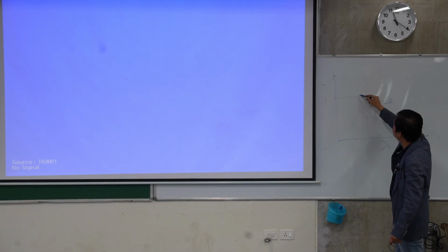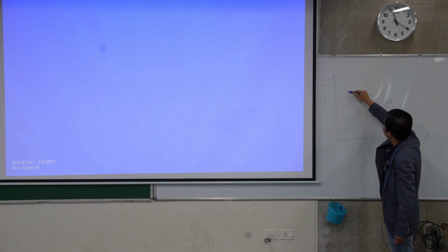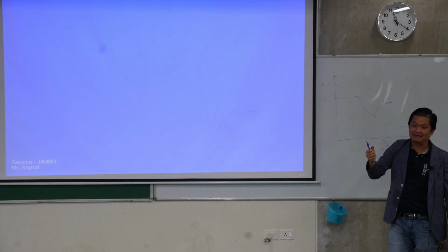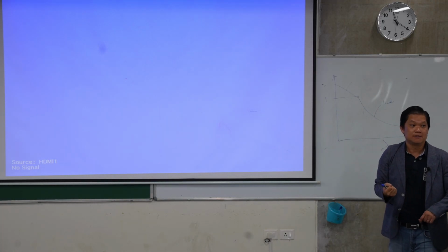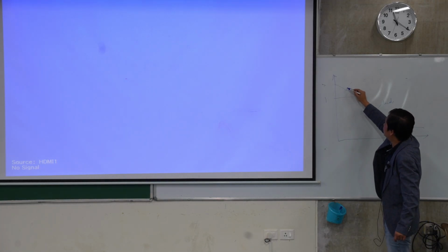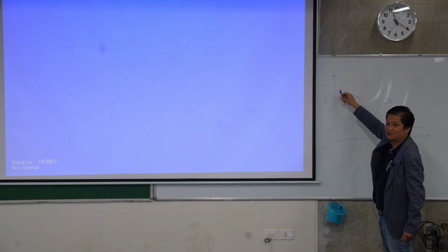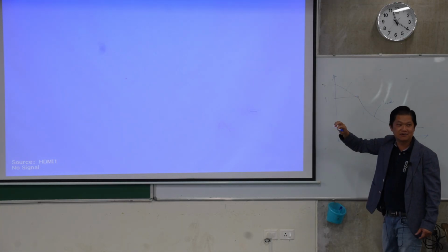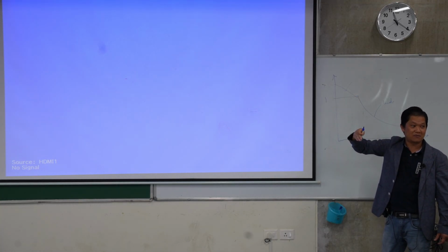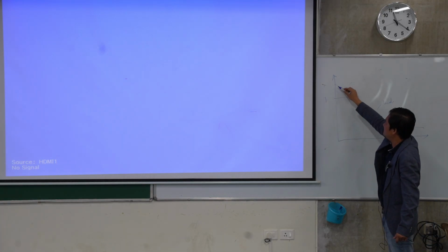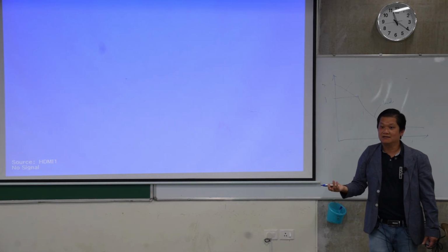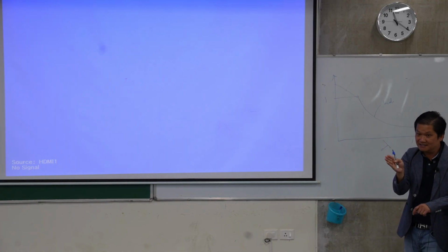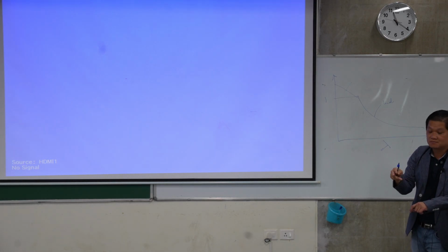But in practice, it's actually from here to here. That is called the inelastic reserve range, and that allows you to design a little less conservatively, closer to practice. So there's an equation in the standard to design for that range.